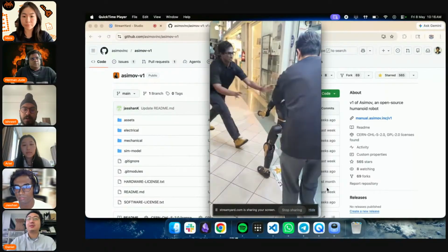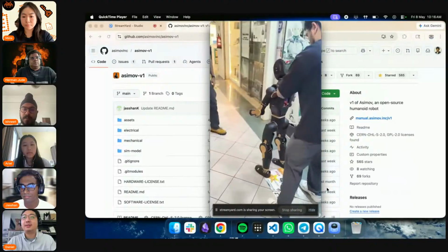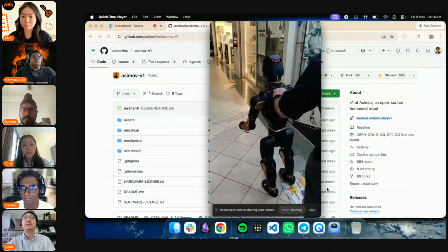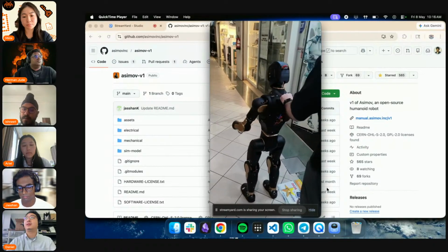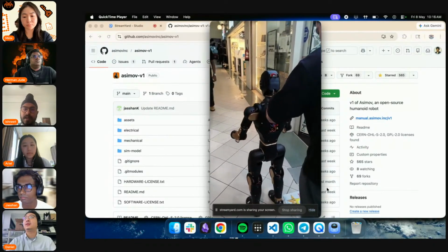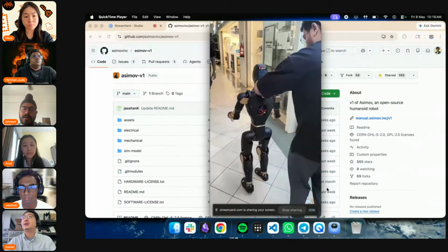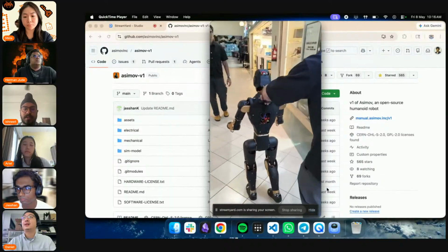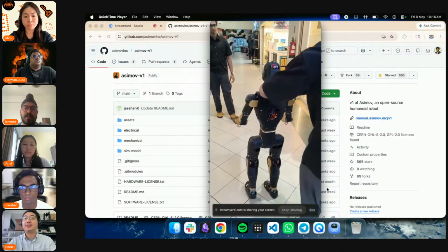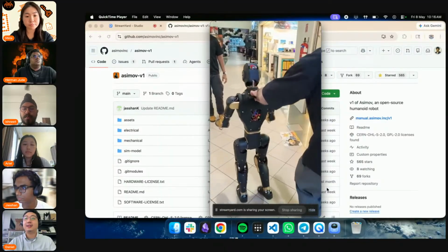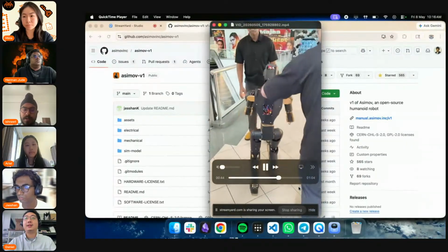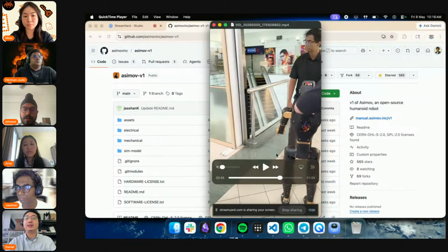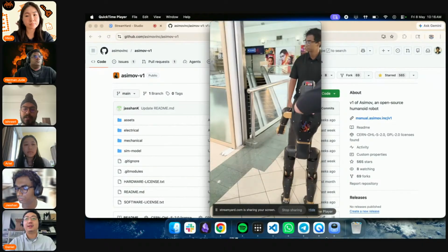We are able to get it working on the robot after we got some hardware fixes. And as you can see, it's not perfect here, and the robot sometimes gets stuck or is leaning forward. The main two issues we identified that we want to solve are, one, the robot generally tends to lean forward. It could be that the policy learned a dynamic and we need to model something correctly to improve this. As well as, you've not seen this video, but sidestepping was an issue. We were not getting determinism with sidestepping. Sometimes we would just wildly swing its leg.